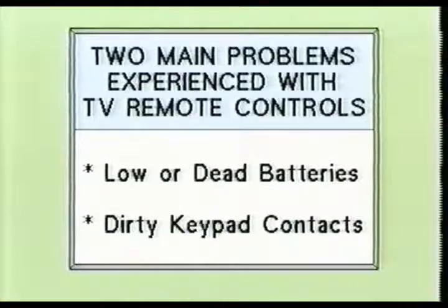The two major problems a technician will encounter with TV remote controls are low or dead batteries and dirty contacts within the keypad. Both will make the operation of the remote control system seem sluggish or faulty.